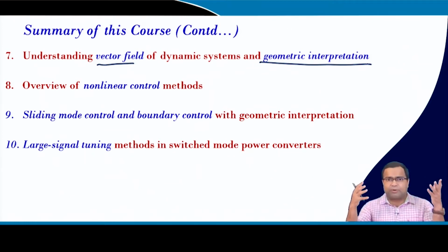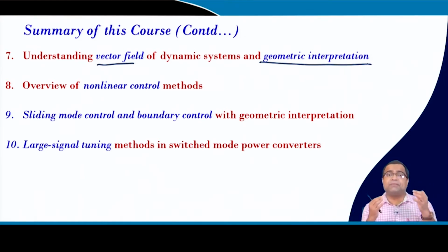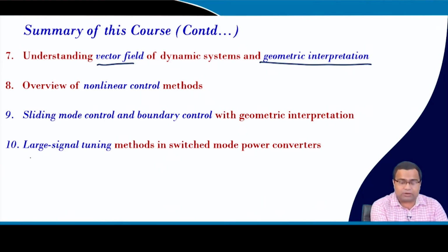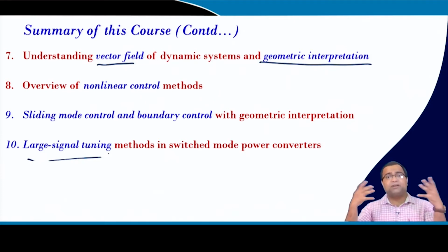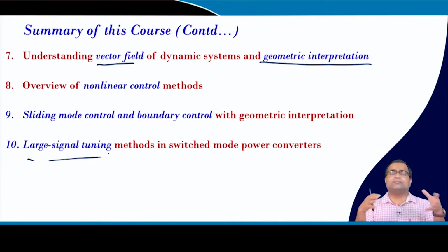So, then we talked about taking just a first order switching surface, which can be framed into a PID controller or a PI controller for current mode control, and then we simply have to get the optimal gain of the proportional controller, which decides the slope of the switching surface. That can go to the fastest response, or close to the time optimal response, and that gives us what is called large signal tuning, which we will also discuss. It has the potential benefit of achieving the fastest response even using our existing current mode control or voltage mode control, by incorporating the current ripple.